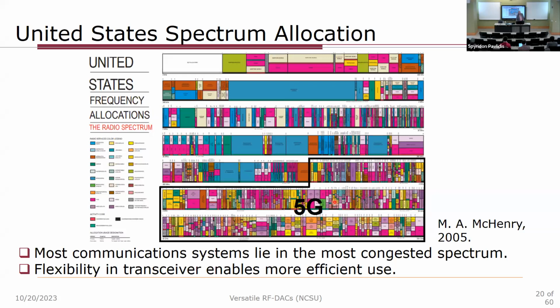It's speculated that in 6G, they're going to actually roll back and start using centimeter wave frequencies, what they're calling FR3, that exists between 7 gigahertz and 24 gigahertz. It propagates a bit better than millimeter wave frequencies, has better latency, but also gives you some more bandwidth as compared to the sub 6 gigahertz frequencies that are commonly used in 4G.